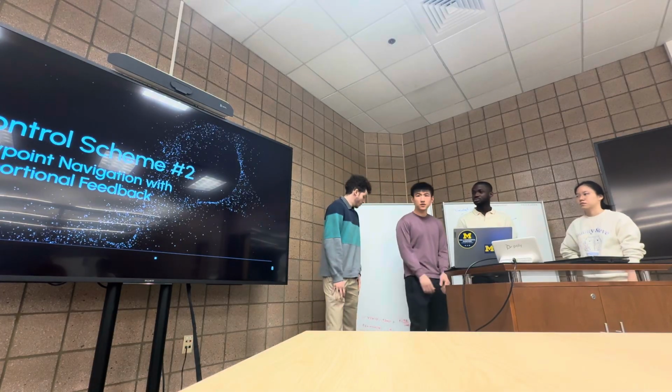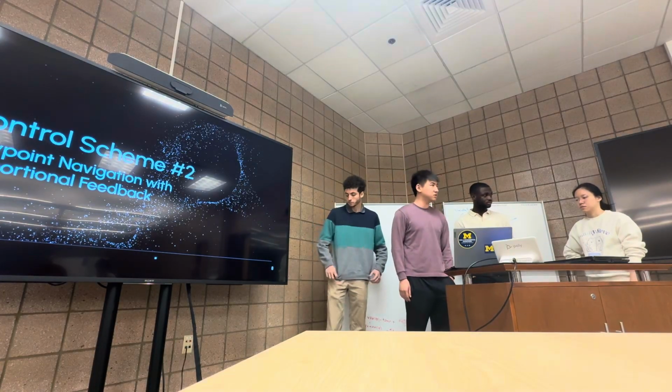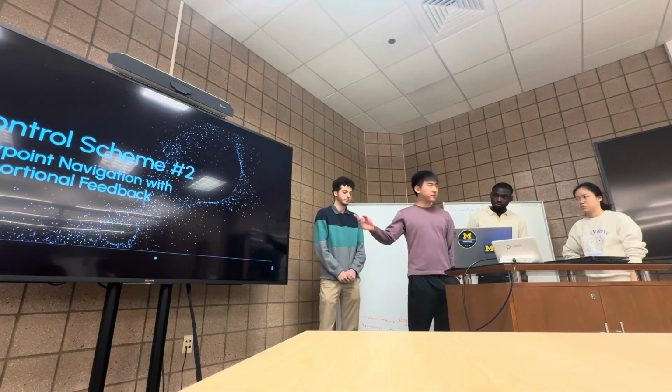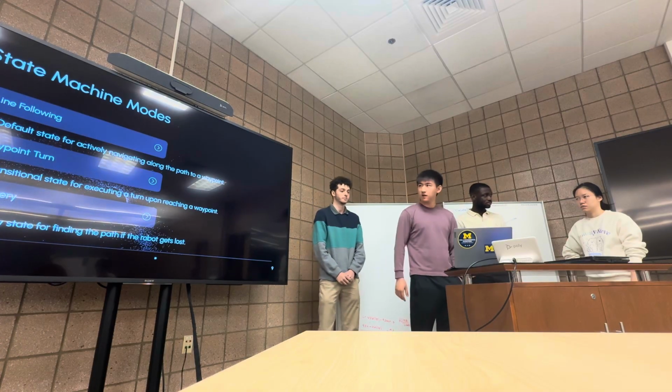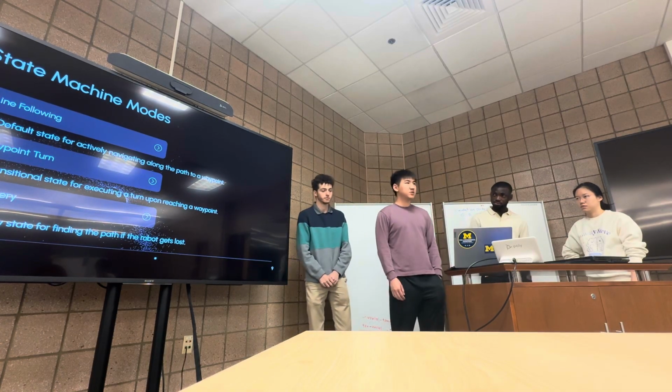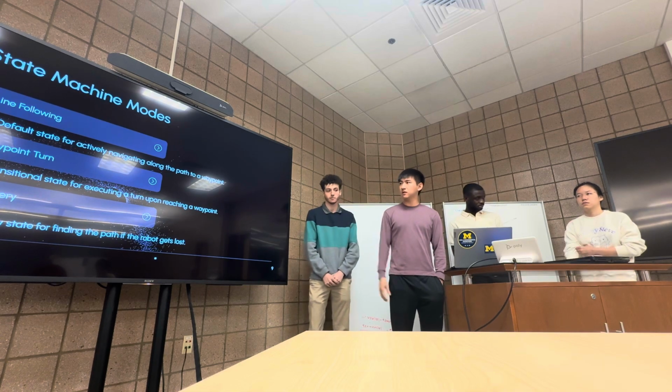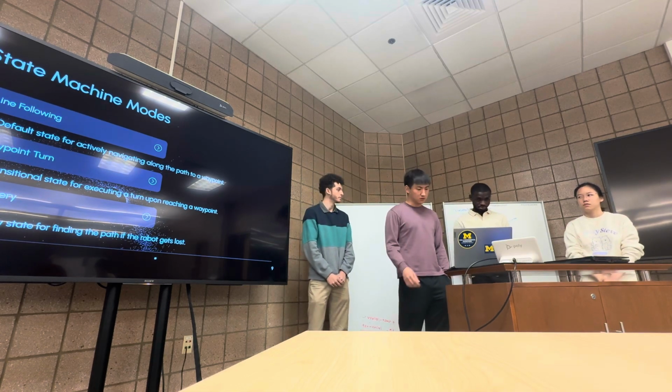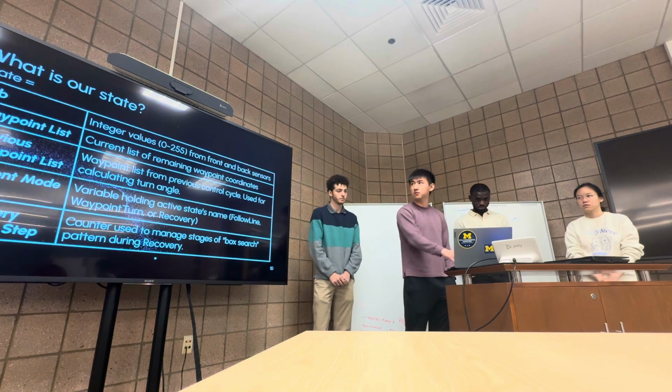Okay, so now going on to our second control scheme, which just uses proportional feedback to navigate from waypoint to waypoint. We'll have 3 main state machine modes, which is line following, waypoint turn, and recovery. We'll go more into this in the future.